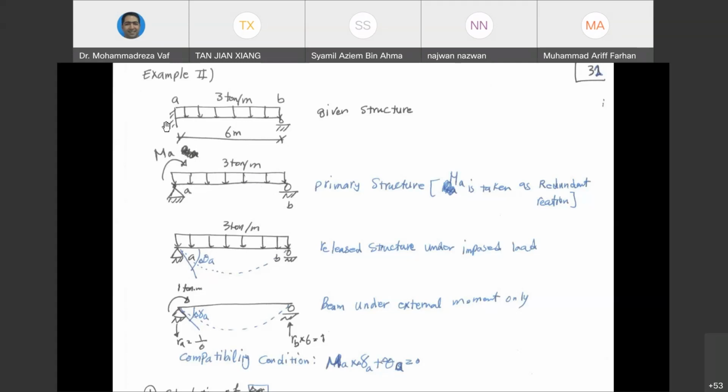But the problem is that the moment that you remove this bending moment, your structure is going to show some rotation over there. We know that a fixed support in reality doesn't have any rotation. So the moment that you remove the bending moment from there and convert it to a pin support, you have also changed the zero rotation to a value that we don't know how much it is. So we need to apply this time a bending moment to that specific location and make that rotation equal to zero. Because in the first place, in the same structure, we didn't have any rotation at point A.